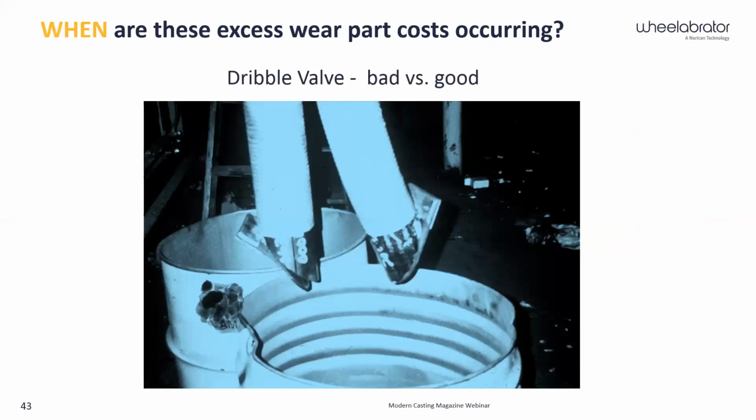Problem is now when my dust collector is drawing air, I'm actually drawing ambient air from down here. So I'm not pulling all that air across that separator curtain. I'm pulling it up this tube. So I'm not as efficient at the separator curtain. These things are all designed so that with a certain amount of weight of the fines, they kind of burp. They'll slowly open up to release the trash and contaminants into a barrel like that.